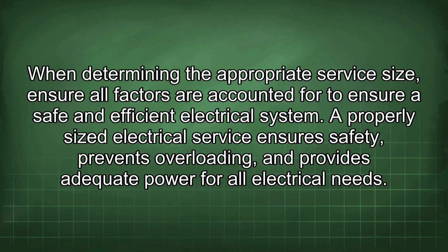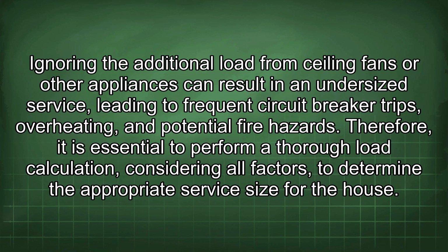When determining the appropriate service size, ensure all factors are accounted for to ensure a safe and efficient electrical system. A properly sized electrical service ensures safety, prevents overloading, and provides adequate power for all electrical needs. Ignoring the additional load from ceiling fans or other appliances can result in an undersized service, leading to frequent circuit breaker trips, overheating, and potential fire hazards. Therefore, it is essential to perform a thorough load calculation, considering all factors, to determine the appropriate service size for